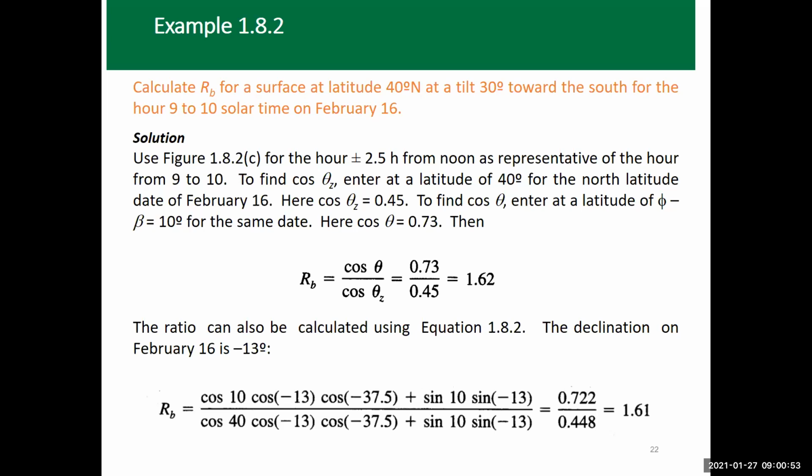So what you do here, number one, look at the hour so that you can pick up the figure. If you remember, figure A was handling 11 to 12 and 12 to 1. Figure B, 10 to 11 and 1 to 2. Figure C is basically 9 to 10 and then 2 to 3. So we should be going for figure C then. February 16 is the day, the line that we're going to select from the figure to get the value.